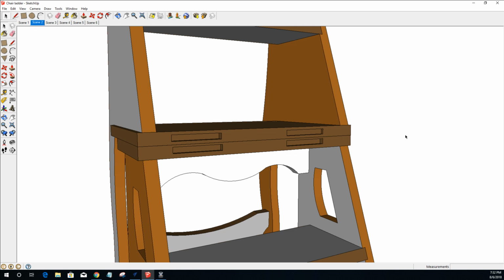Now, if we did do them on a CNC, then they would not be hidden. We could cut from the edge and pocket down, but I don't recommend that, because then when it's folded into chair mode, now you have these little square holes in the top of the chair where you can see. So I recommend just hidden. That's why they're called concealed hinges. And you can source them anywhere relatively inexpensively.